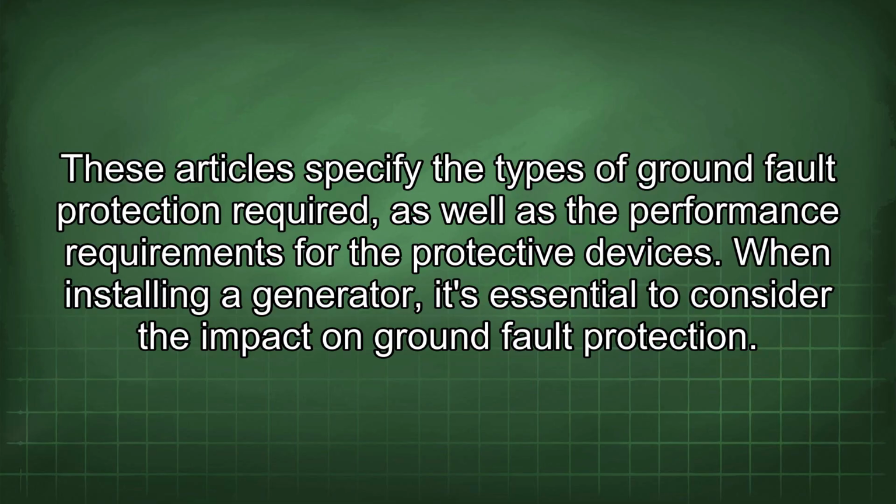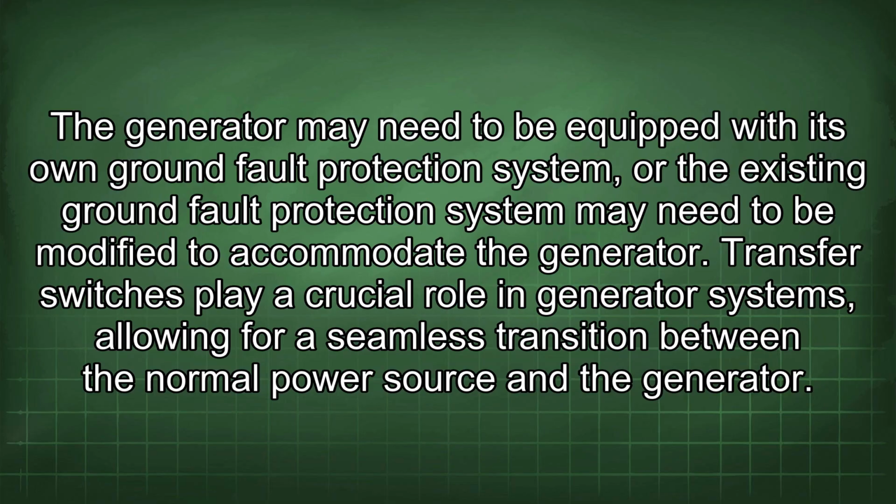for the protective devices. When installing a generator, it's essential to consider the impact on ground fault protection. The generator may need to be equipped with its own ground fault protection system, or the existing ground fault protection system may need to be modified to accommodate the generator.